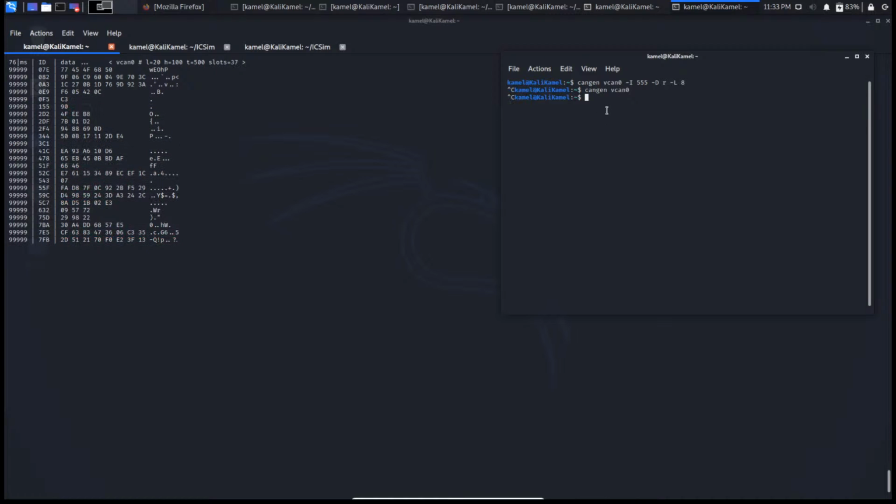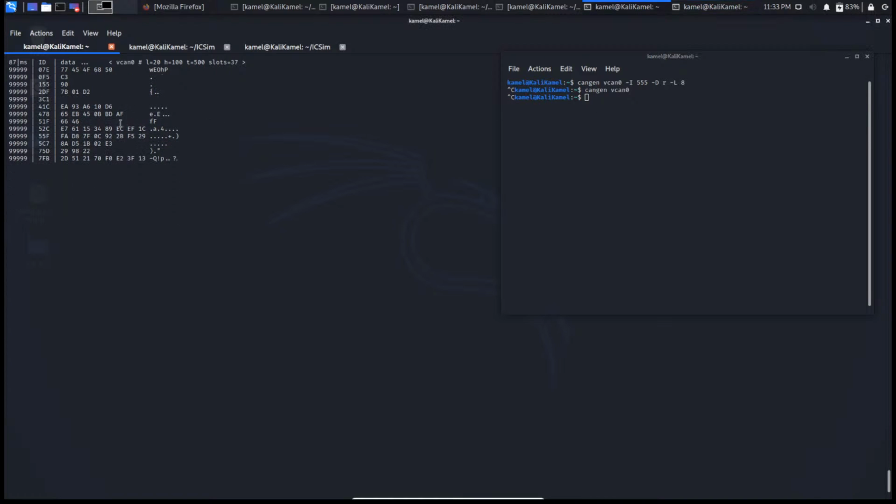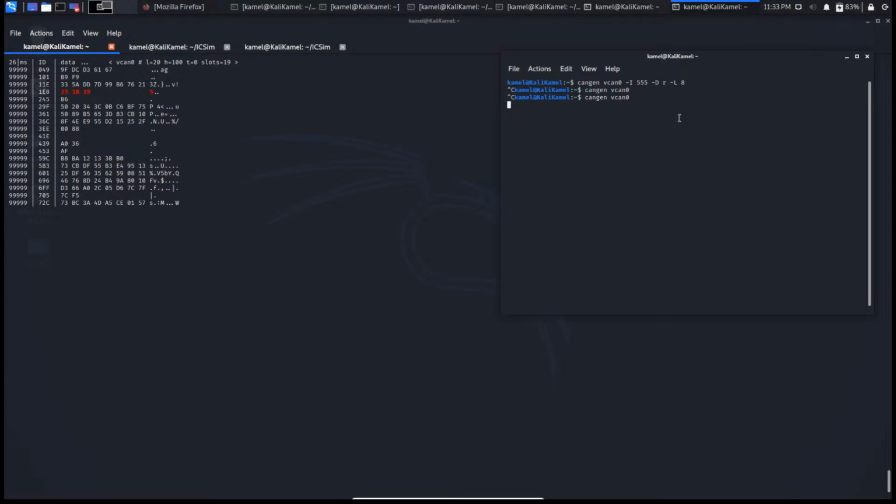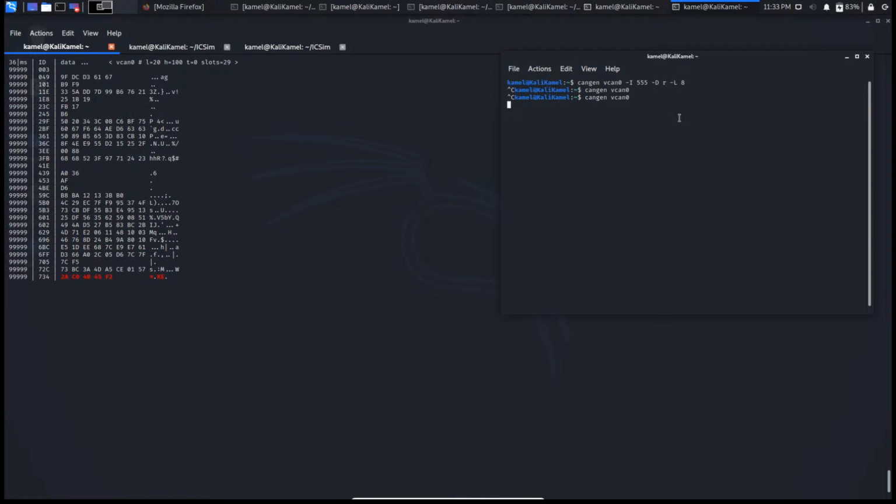So I'm going to hit pause, and oh, it's all disappearing now. I forgot to use the other one, the -T0. This makes it so that there's no timeout for the data, so that it stays on the screen the whole time. So let's just run this again real quick. Sorry about that. I made a little mistake there. Forgot about the timeout on CANsniffer by default.